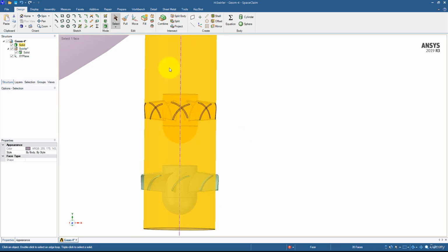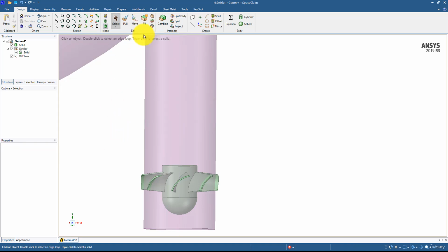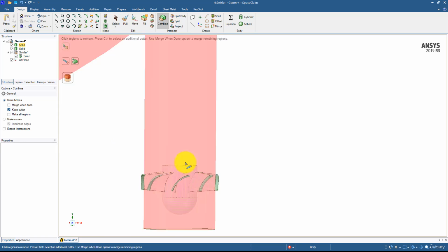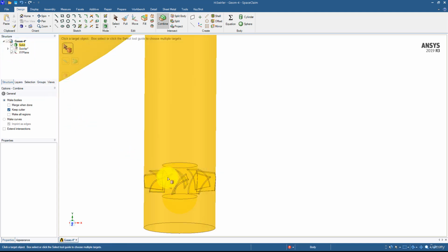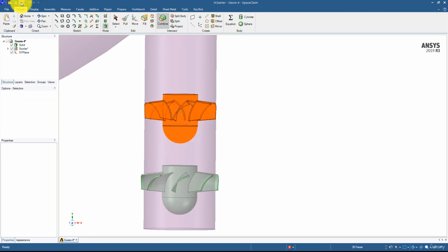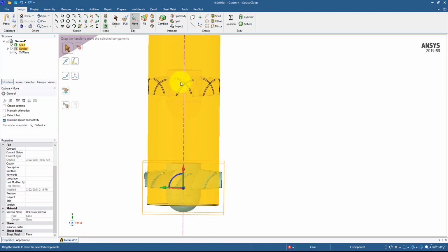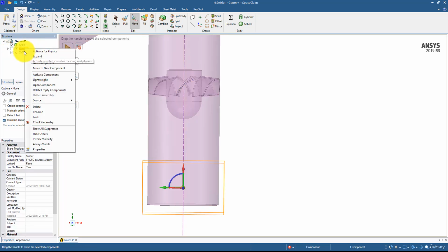I can choose this geometry, which is now part of our main geometry, and use the fill command, and then again use the combine command and delete this geometry from this main model. So this will create this geometry over here. You can see now we are able to create the same geometry over here. So we can undo here, and we can create the same thing back at the 191 millimeter height.